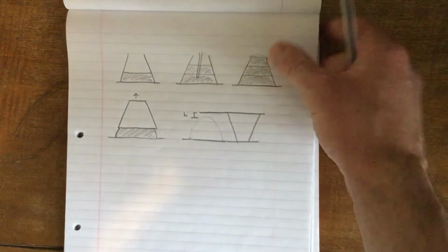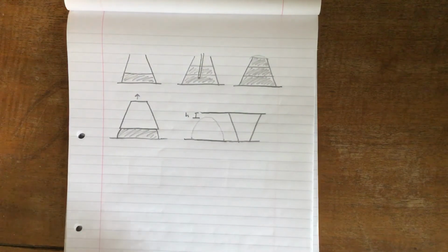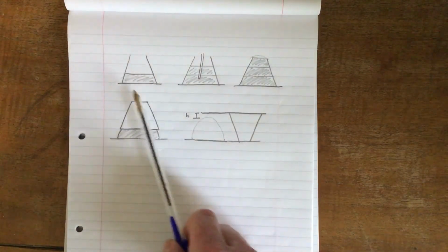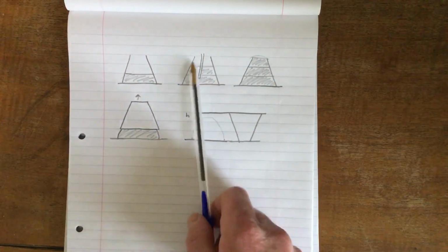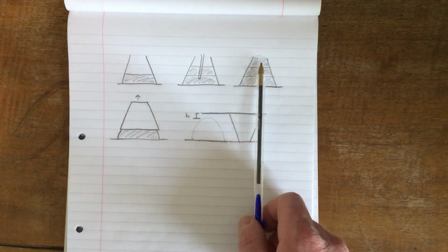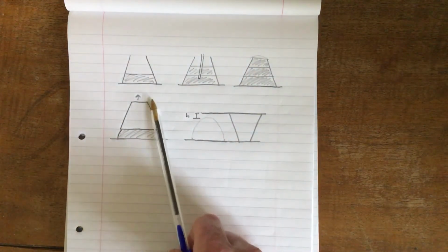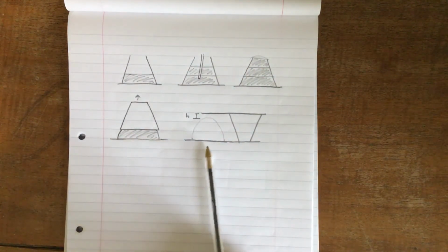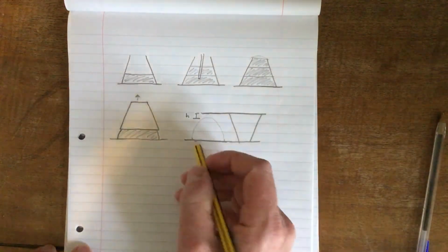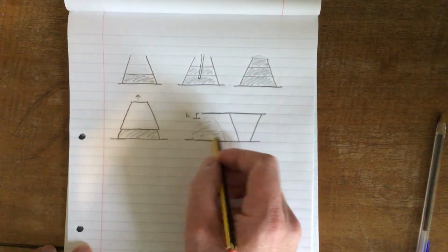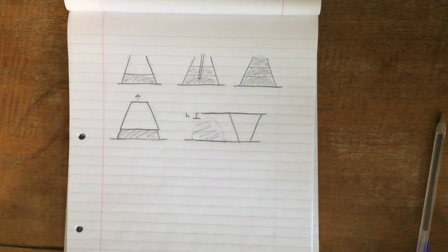So here are my sketches for my slump test, really quick and simple ones. I have my mould around the outside, 1 layer of cement in, 2 layers of cement in with a tamping rod, 3 layers of cement in. Then I pull up the mould and my cement comes out the side. And then my third sketch is the slump where it comes down, and there's my cement that has fallen off.